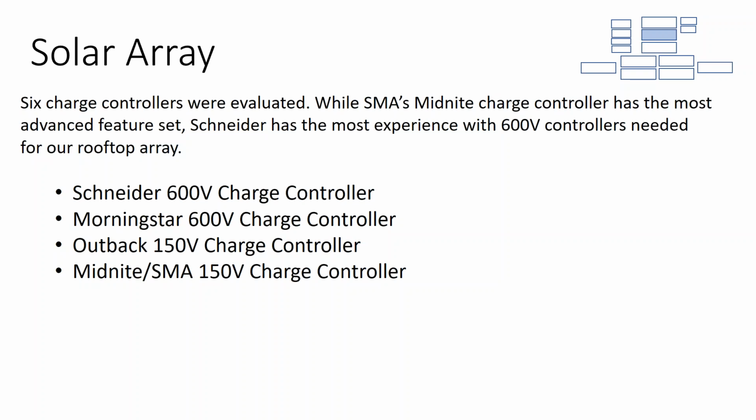In researching this class, I came across a National Park Service project up in Alaska where they actually have dozens of charge controllers on an off-grid array. The charge controllers are programmed to rotate in operation, so there are more charge controllers than they need, and they rotate in and out so that they're always being tested, but they're never going to run out of power at this remote site.